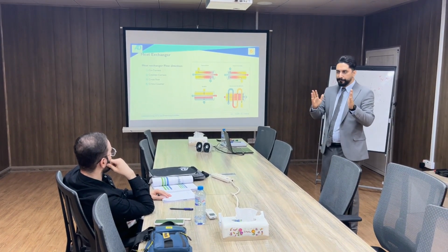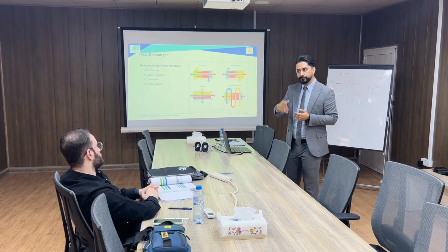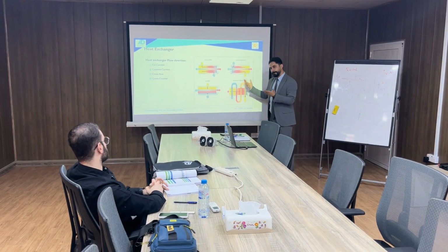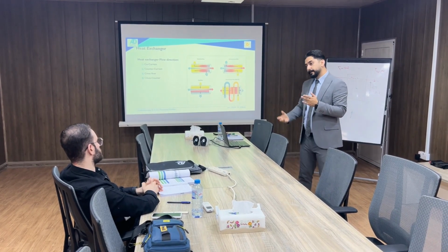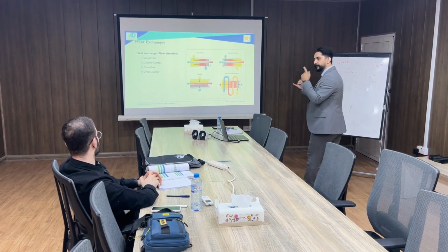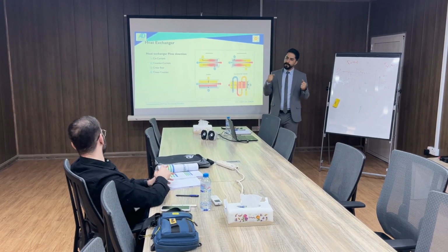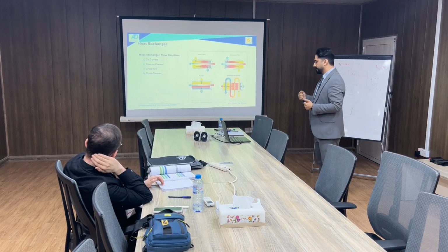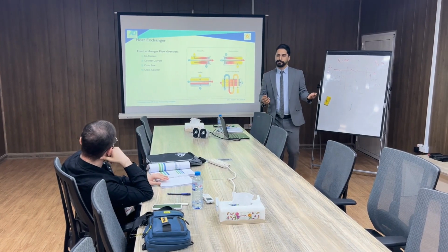By installing a baffle, the fluid available in the shell is going to pass through the tubes in cross, hybrid, or mixed flow. You can find all of these different names in the references, and this will increase the amount of heat transfer. Okay? So by checking the formulas and knowing the different types of flow direction, we can understand which one is the most effective one. And when we are talking about effectivity, it is actually energy consumption. Okay?